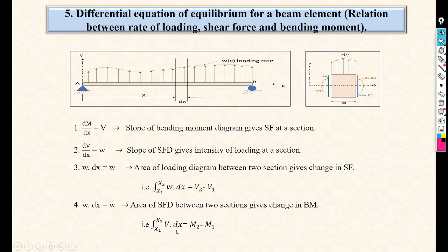In simple terms, the derivative of moment gives shear force, the derivative of shear force gives loading, integration of the loading diagram gives shear force, and integration of the shear force diagram gives the bending moment.